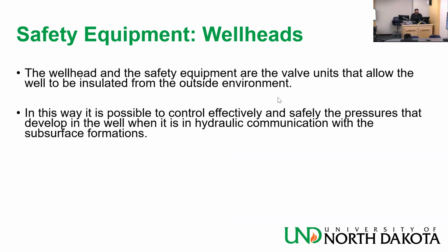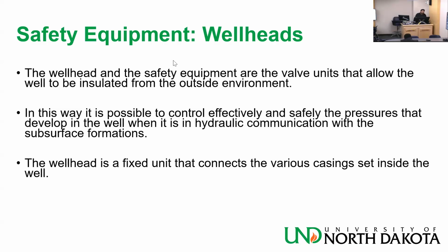In this way, it is possible to control effectively and safely the pressures that develop in the well when it is in hydraulic communication with the subsurface formations. So when you are drilling, if you haven't set casing yet, you are really interacting with the formations you are drilling through. That's why I say BHP must be equal to FPP. Otherwise, I get fluids from the formation into the well. That's basically a kick.